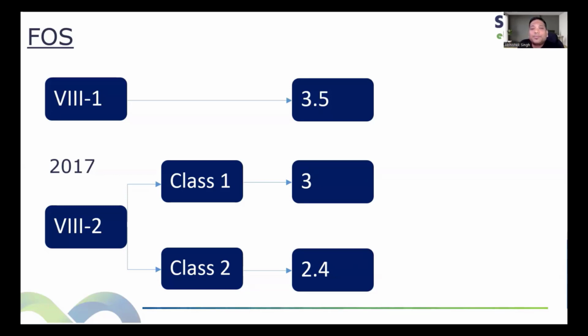If Division 2 comes to your mind, like if you see Division 2 code, we always think that we have to perform FEA. So what is the answer for that? Do we need to perform FEA if my code is Division 2? No, we don't have to do FEA for Division 2. But before 2017, that was not the concept. When you were following Division 2, you had to do FEA.